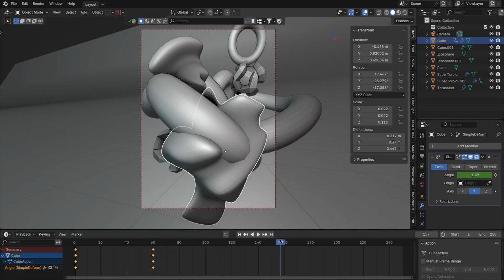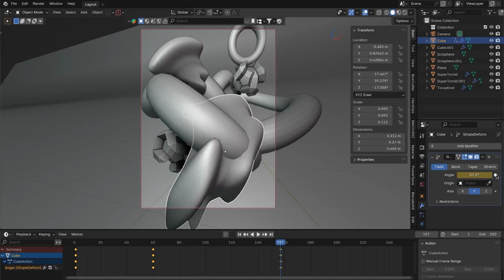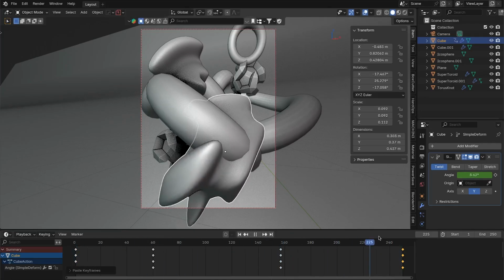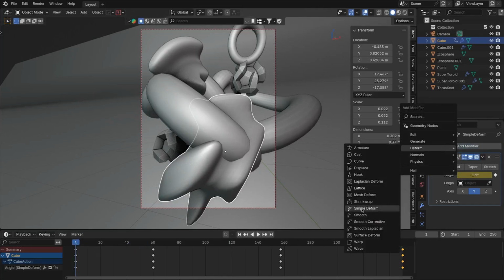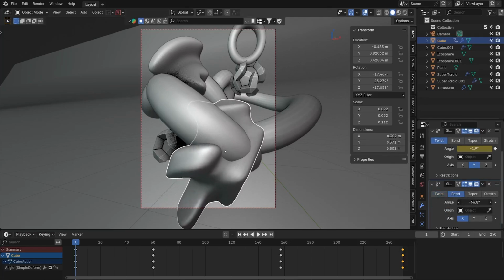And now that transformation is going to go across the whole timeline. So I'll do another keyframe there. I can just press that diamond. Then I'll grab my keyframes at the front, copy paste them to the last frame, and now we have a fully looping animation. So after this, we're going to go through and just stack these animations until everything is moving and flowing and we get some really interesting stuff going.